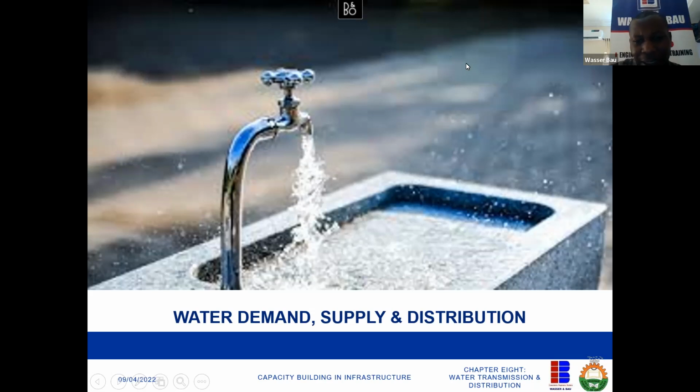After that, you look at the layout and do the water demand calculation. In doing the water demand calculation, you must take cognizance of three things. What is the population equivalent of the people? Based on household, you might discretize it: from household, you move to regions, from region to district, in terms of subsets, subgroups, and clusters. Then you calculate the total. That will be your average demand.